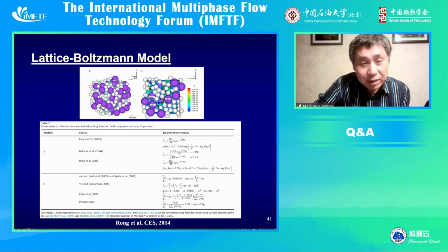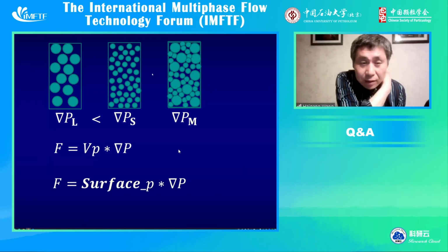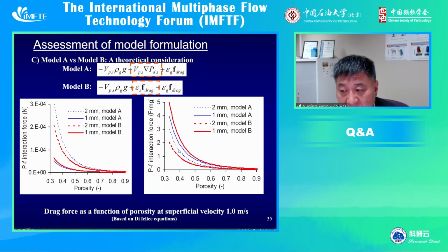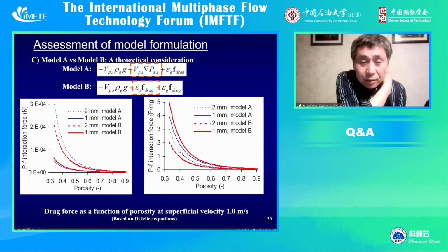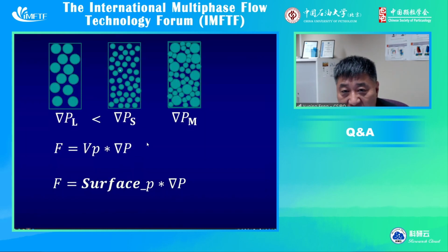If the pressure, you see here, very interesting. This one, the pressure term, we call PD, dynamic pressure. That's by drag. If we use a traditional CFD, only one pressure gradient, but we have different particles. Based on the volume fraction, each particle contributes the drag by its volume, like a buoyancy force, like a particle in the water. It's the static buoyancy force, but the contribution of the PD, this dynamic drag, because of relative velocity, small particles contribute more than others.